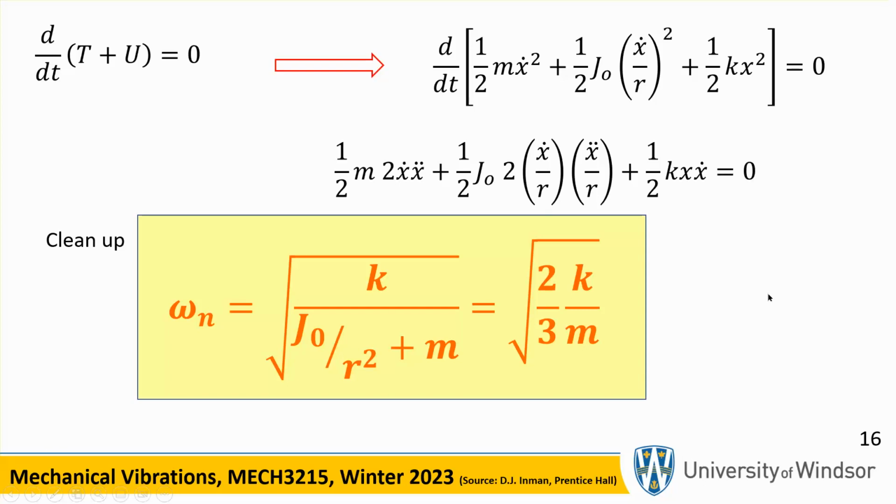Now, in lecture 4, because I did it using Euler's method, Newton's second law, Newton-Euler's law, which is taking moments, I had to draw the free body diagram. I have to include the friction or rolling force, etc. So although this is a little bit harder, it's not a complicated problem. We could do it with Newton's second law, but here we did it with the energy method, which is a little bit easier. Now, incidentally, how you go from there to there is that for a disk, J_o is 1/2 m r squared.